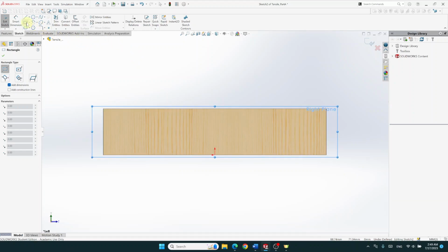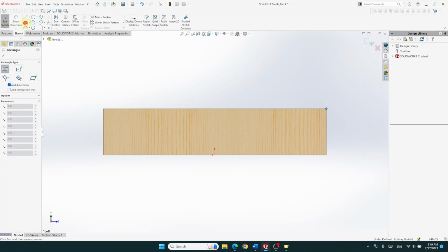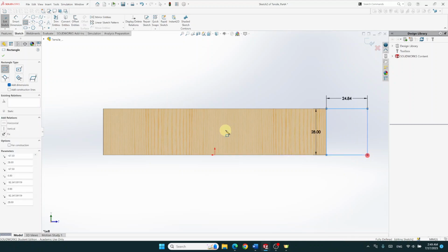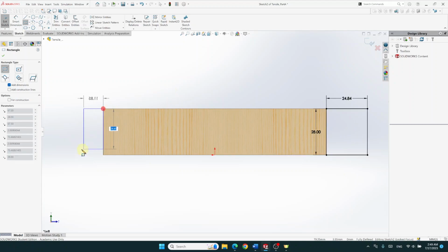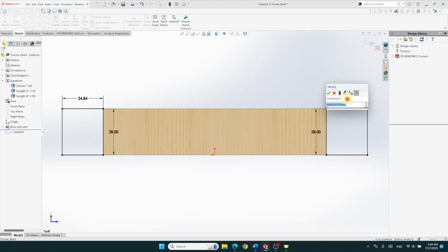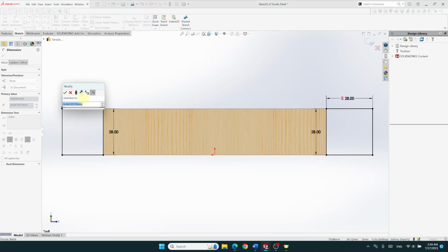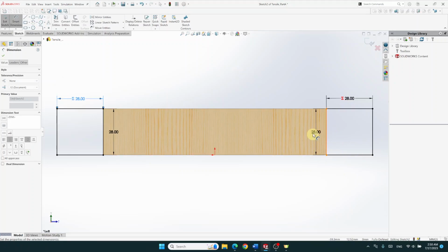Here we go. So I will add 2 little squares. Oops, I forgot to click on the rectangle. I can select this one to this one, and this one to there. And I will add the dimension. So that's my section. That's also 28, equal global variable section. Enter. This is black. Double click. Equal global variable section. Enter. And you see it's black because it automatically fits with the bottom there.